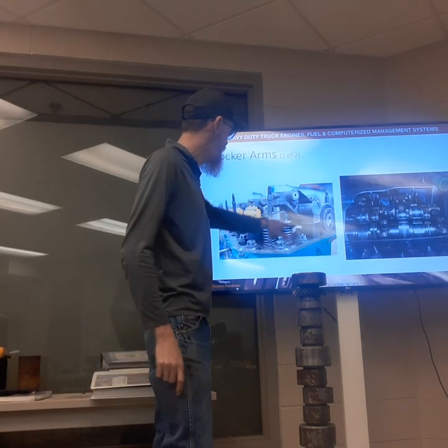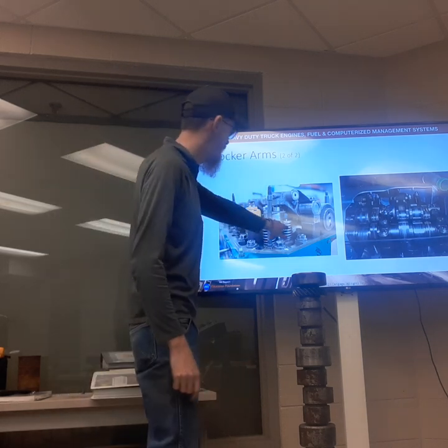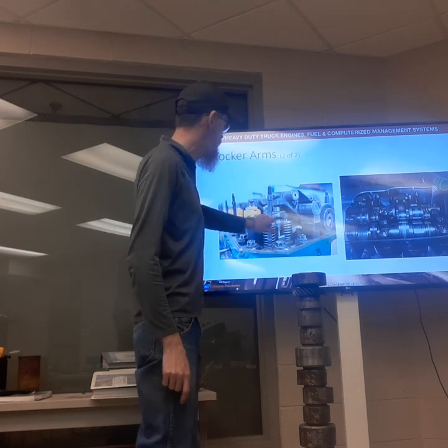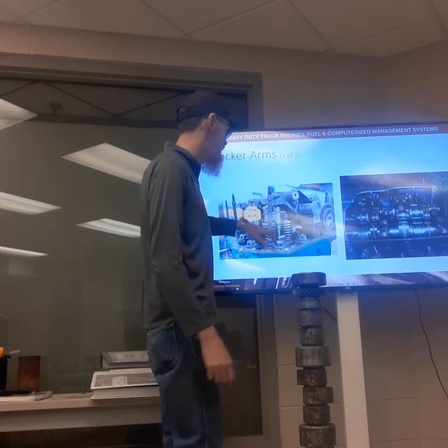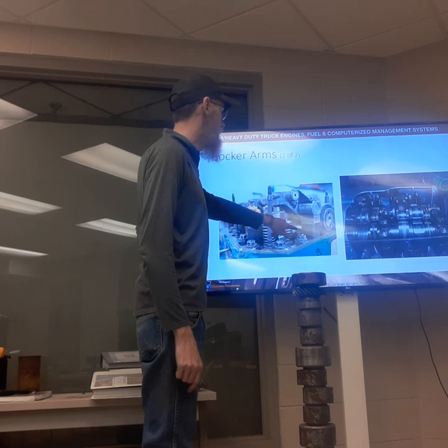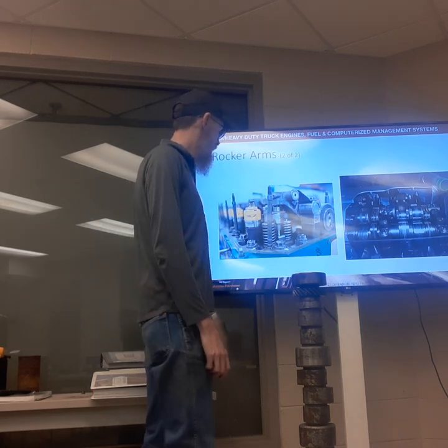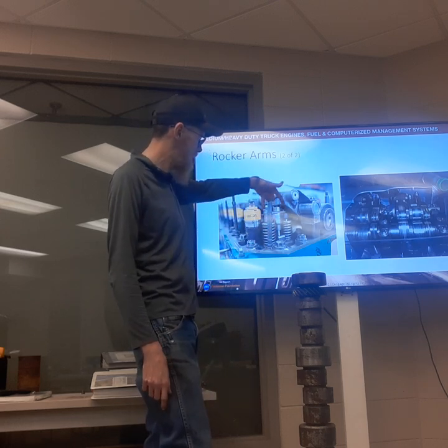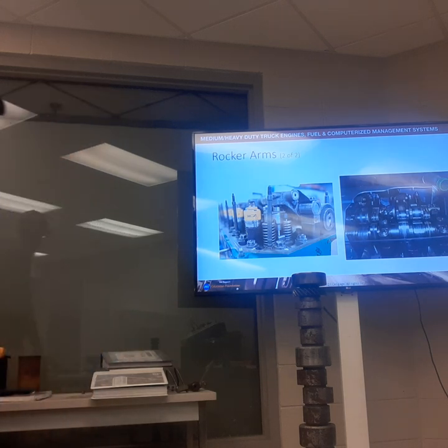You can see it in this illustration here on the PowerPoint slide. You can see our two valve springs, and right on top of those two valve springs, we can see the rocker bridge or the valve bridge. And ultimately, that is a component that goes between the two intake or exhaust valves that allows us to use one rocker arm to push and actuate two valves.